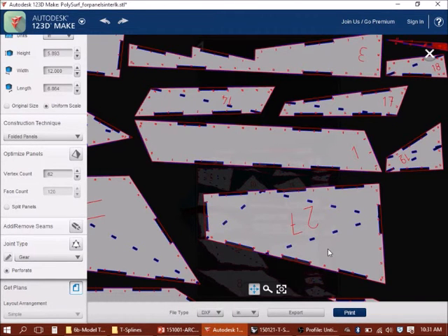So if there are bits of text, or other patterns that you want to be present on these, that's something that could be overlaid and either etched onto these panels or actually cut through these panels if it's a series of openings coming from the abstract expression. If there was a perforation pattern or a series of circles, I can create those circles using Rhino, bring those into the same file as the laser cutter, put those in place, make sure they're in the right scale, and modify these panels so they become a little bit more expressive. So you might be able to see through some of these panels to the structure within.